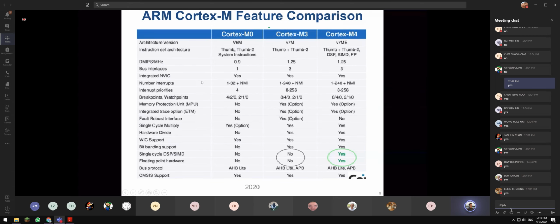Of course, the most popular Cortex microcontroller is the Cortex-M4. This is the one pre-built into the Nucleo development board from STMicroelectronics. Why is this so special? Because it has a built-in DSP with single instruction multiple data. This means that one instruction can carry out a few tasks. I believe most of you already learned this in the subject computer architecture. And of course, they also have built-in floating point hardware. This is why the Cortex-M4 is so unique.